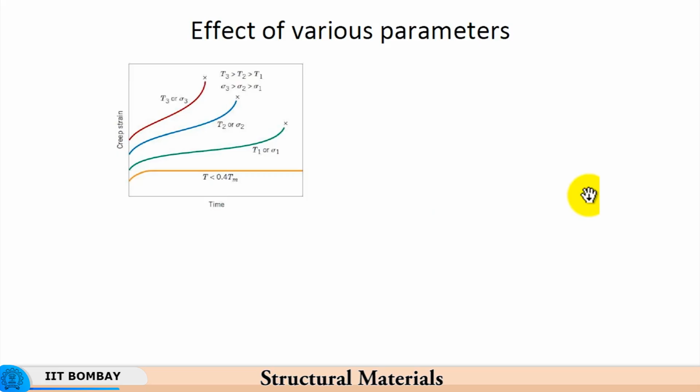So, with these creep curves, one can, to start with, design a product that will last a certain duration. So, the life of the component subjected to creep is assured by design. Then you would monitor the creep strain from time to time based on the temperature and stress that is acting on the component, and then decide on its maintenance schedule. So, it is possible that the in-service conditions for some reason lead to an accelerated creep or more creep strain than what was anticipated, and therefore you might have to monitor the creep rate.